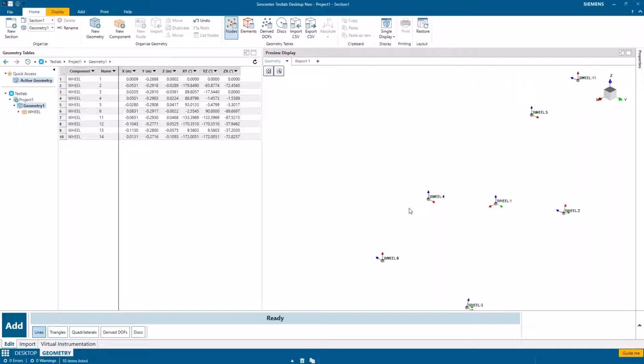If you just laid out points in space and you haven't put a transducer on there with a specific orientation, they might do it differently than you expect them to, and then you've got the old rolled accelerometer problem where you have phasing issues and the directions are wrong. This virtual instrumentation is alleviating all of that kind of error-prone stuff.